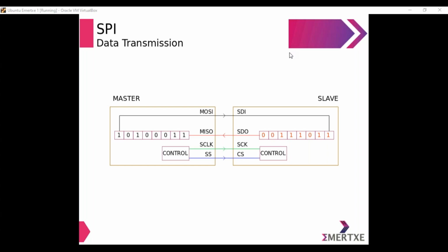Similar to the UART protocol, whenever you had to transmit some data, were you able to transmit it directly from a pin of a microcontroller? No, right? So first you have to write the data to the buffer register. Then from the buffer register, where was it going? Yes, it was going to the shift register. Then from the shift register, data was getting shifted bit by bit.